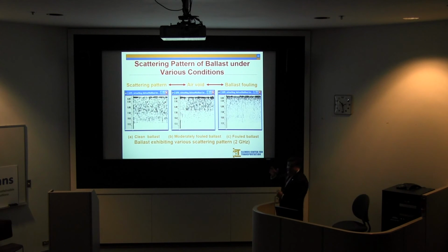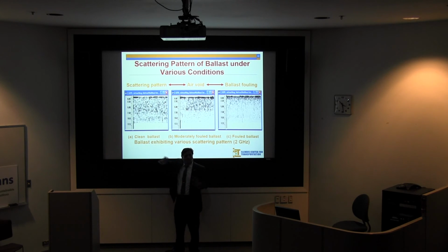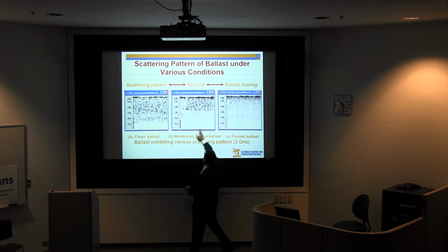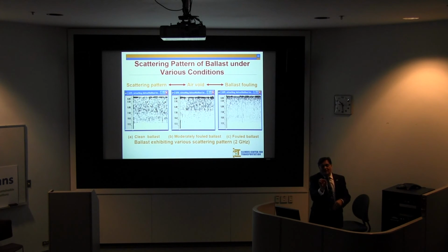In railroad, this scattering that I'm seeing, if you have clean ballast, you see it just like this without any analysis. If the voids are filled with clay, you see it like this. By looking at these two, can you see the difference? Without analysis. This one here is a complete scattering because the wavelength now is closer to the void size, so you have internal scattering. But in asphalt concrete, the wave is too big to see this kind of scattering. I did mention that you lose some power while you are going because of these little scatterings, but they are not that much.